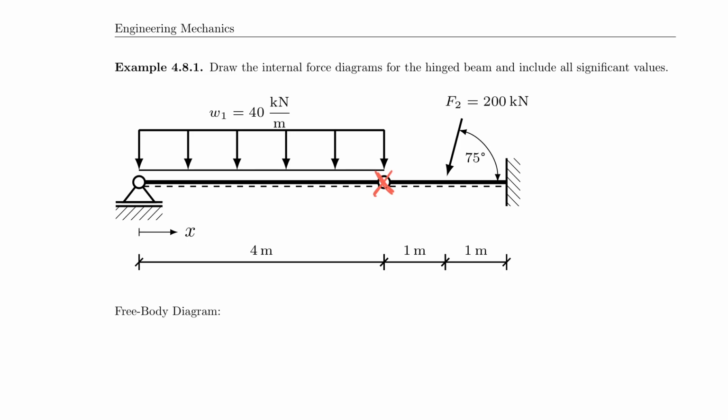I know that my shear force in this first domain, let's call it domain 1, domain 2, and domain 3, V must be linear, constant, and constant.